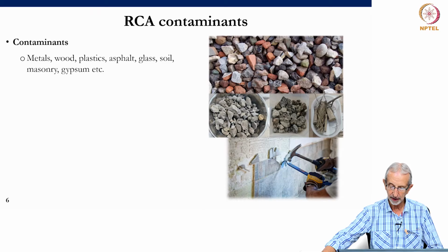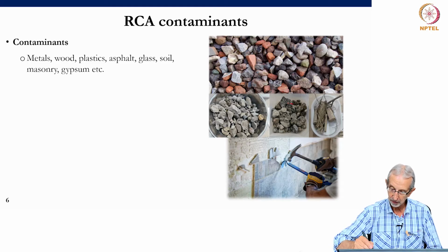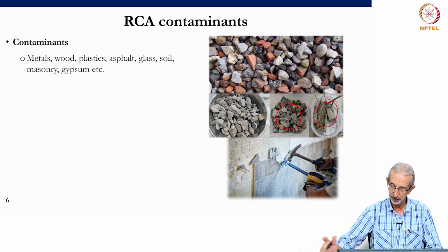But on the other hand, you get these other sorts of things here. You can see the very angular and jagged particles, the coarse surface in this middle diagram here, which is really not very good material at all. There's even some wood and twigs and other stuff over here, which we certainly don't want in our concrete. And when tiles are broken off the wall, then those tiles can land up as well.